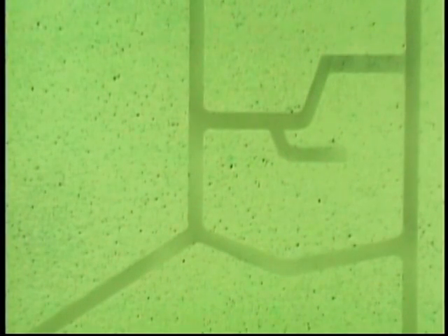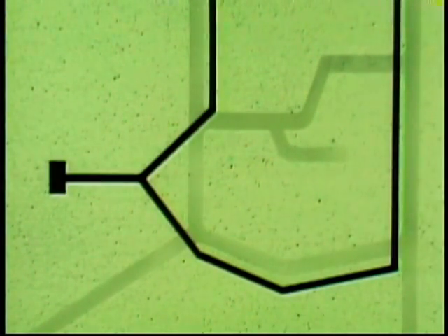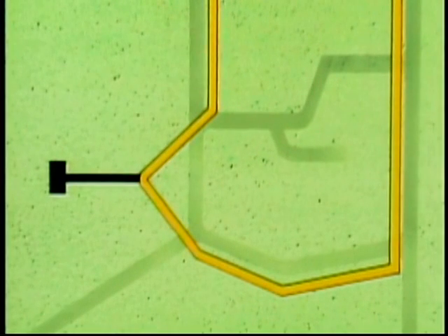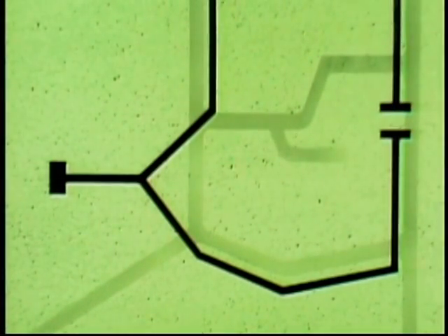A primary system with a loop circuit layout extends from a given point and loops around back to itself. The loop circuit may be operated as a closed loop, as shown here. This means that there are no breaks in the loop. A loop circuit may also be operated as an open loop. This means that the loop is not continuous. There is a normal break in the loop.